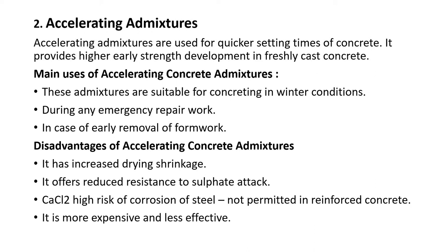Accelerating admixtures are used for quicker setting times of concrete. They provide higher early strength development in freshly cast concrete. Main uses of accelerating concrete admixtures: these admixtures are suitable for concreting in winter conditions, during any emergency repair work, and in case of early removal of formwork.